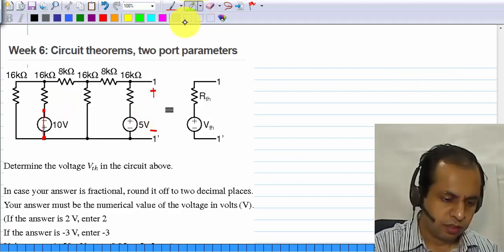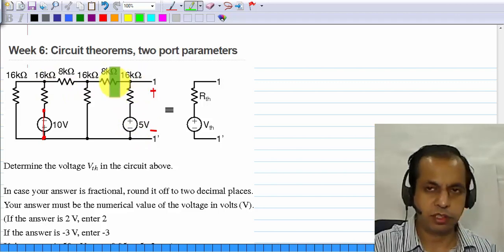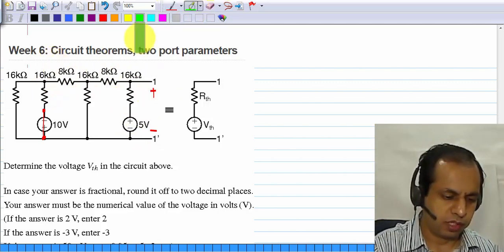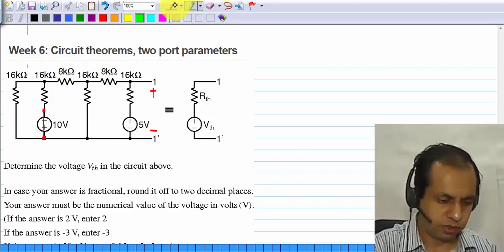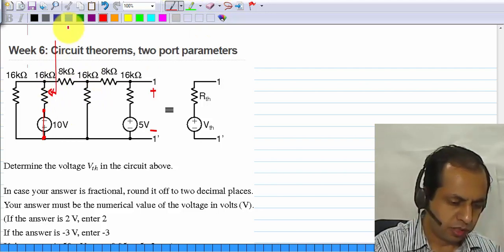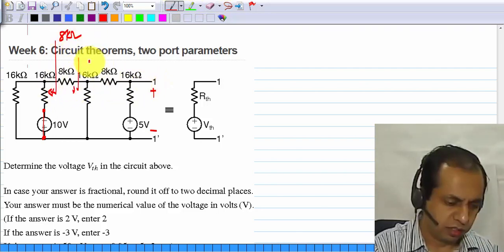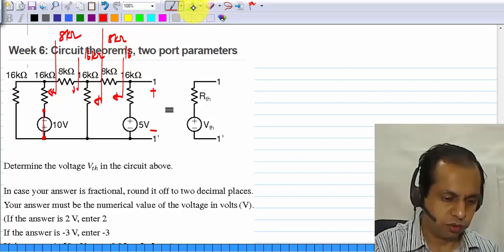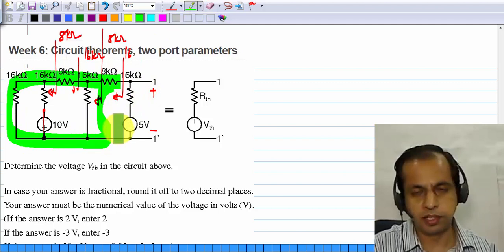Then we'll have a single voltage source and some resistors. You have to find the division ratio. And this particular circuit, it's an R2R ladder where we have 2R branches this way and R branches that way. So it's quite easy. Looking this way, we have 8 kilo ohms because of 2 16 kilo ohms in parallel. Here we have 16 kilo ohms. Here again we have 8 kilo ohms and 16. So all of this appears as a single 16 kilo ohm resistor.